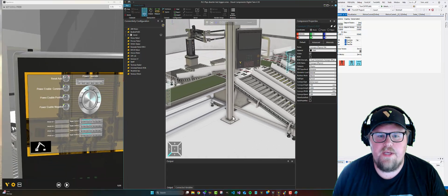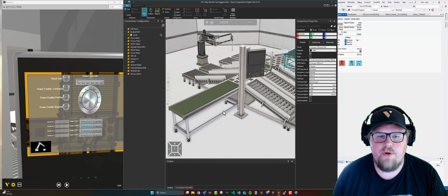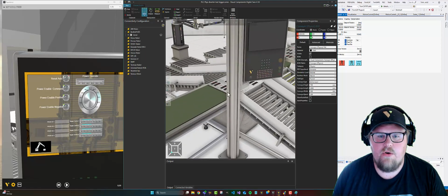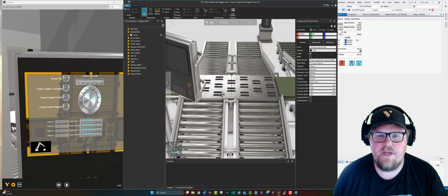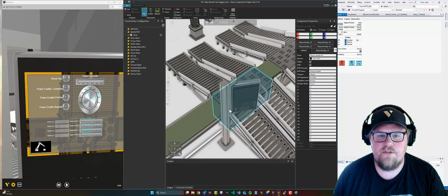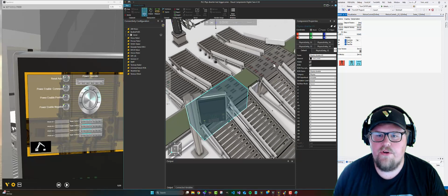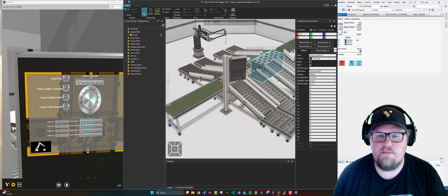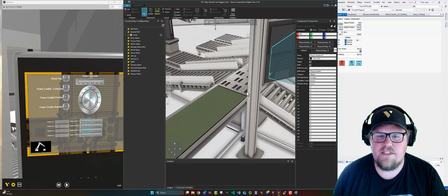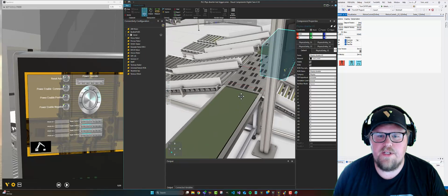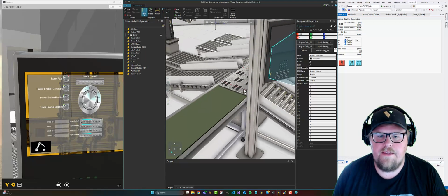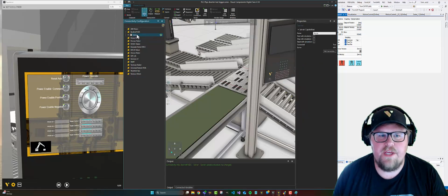Okay, when we hit play in the 3D world, we will basically get some products over here. We have some sensors set up that basically whenever a product hits the sensors, we will get product IDs. So product ID 1, 2, 3, and 4. These are read by the PLC, and the PLC is then tasked with controlling the movement of these diverters. But before we can do that, we need to connect our application with the TwinCAT PLC.